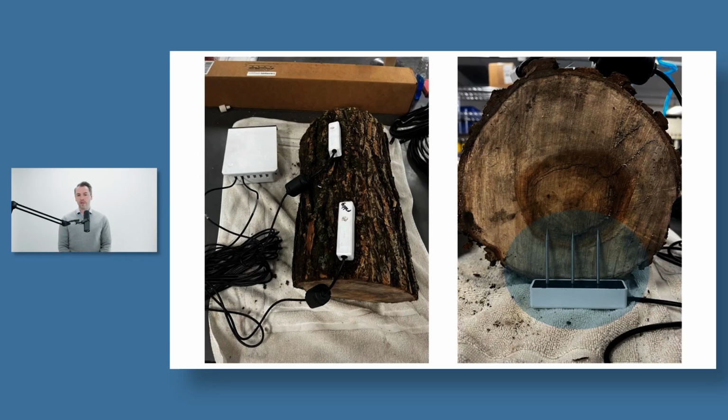actively moving water. So to combat that, we took half of our sensors and we cut those prongs in half. So we have some sensors that are clipped and some sensors that are unclipped. And you can see in the picture on the right, that bottom sensor has something scribbled on it, and that says clipped, because some of those sensors were clipped. But that means then that we need additional calibration points. We need a calibration for clipped and unclipped sensors in ponderosa and in willows. So essentially we need four different calibrations. So all that to say, this can be a challenging and time-consuming process to get these calibrations. And that's part of the reason why we undertook this, just for us to understand what it would take to make these measurements.